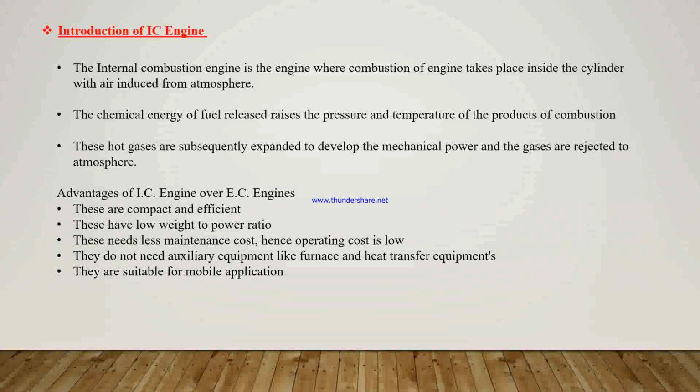Before that, first we see what is engine. Engine is a device which transforms one form of energy into another form. Normally, most of the engines convert thermal energy into mechanical work, and therefore they are called heat engines. A heat engine is a device which transforms the chemical energy of a fuel into thermal energy and utilizes this thermal energy to perform useful work.